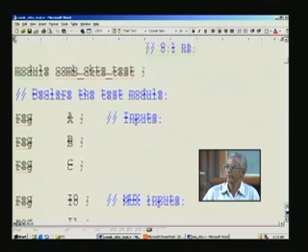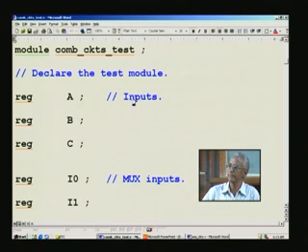Here the difference is that in the design file we declared input and so on, because that appeared right there in the listing. Therefore you will not find any inputs and outputs listed separately here. Instead you have reg and wire, and we will explain why a reg and why a wire. For example, in the design you had all these as inputs, say A, B, C, then I naught and so on. In the test bench, we declare these as reg.